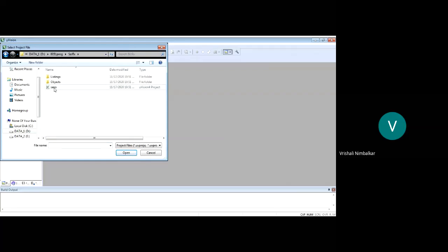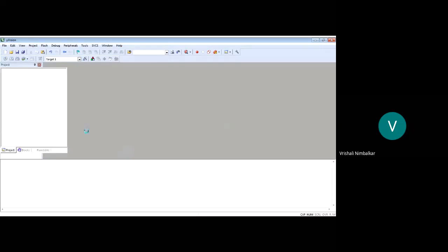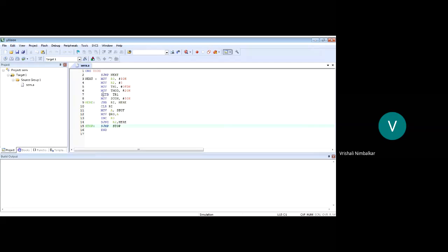Yes, serial RX reception. So see, students, whatever program I was showing on that PPT, the same program is mentioned here. MOV R0, 30 hex, MOV R2, 5 hex, FD loaded in TH1, 20 hex loaded in TMOD, started the timer, SCON register 50 hex, check that RI, clear RI, from SBUF take it in the accumulator, from the accumulator save it in memory, increment that pointer, decrement the counter and repeat the reception, and then we stop.